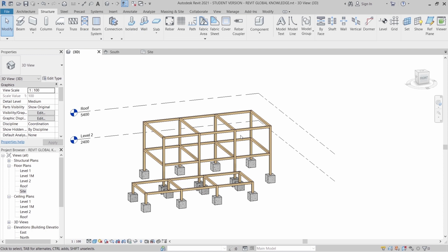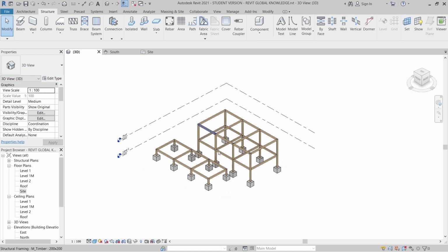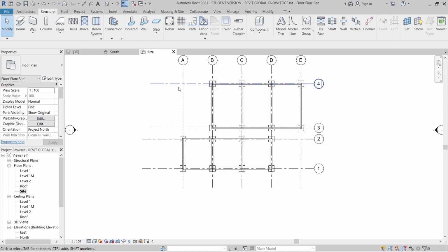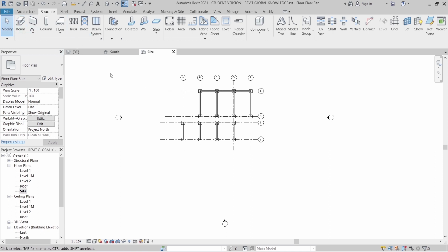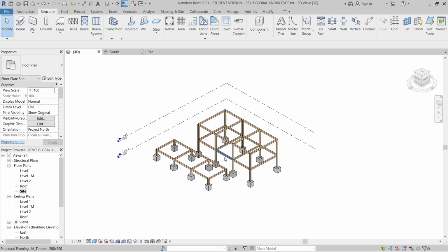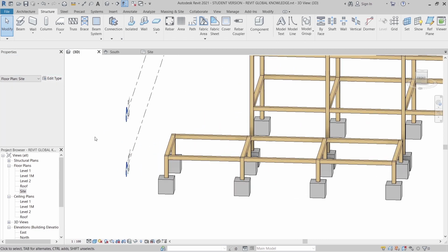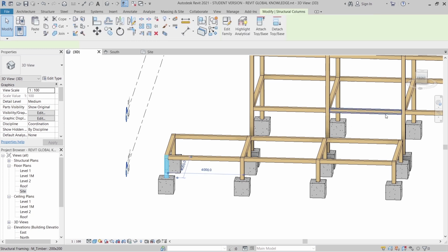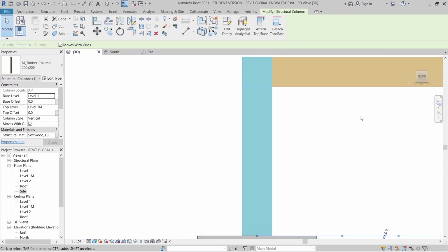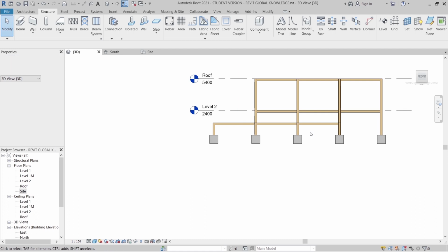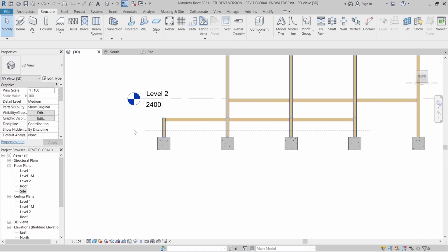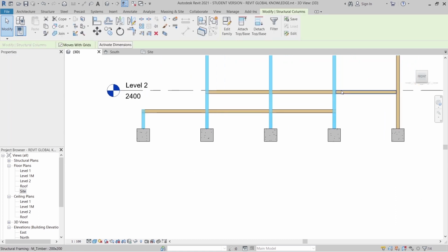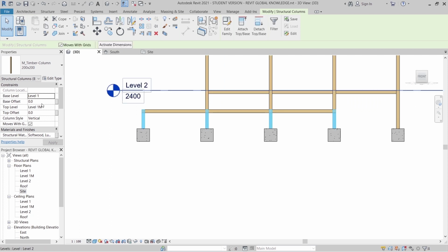So what we are missing is our floor. I'm going to add our floor there. Go back to my site plan there. Go to our floor, but let me adjust here first. I think I got a minor problem over there. If I directly add like this, our floor will be offset a lot. So I'm going to adjust here first. Shift key. I need to minus 150 or minus 100 for our floor spacing.